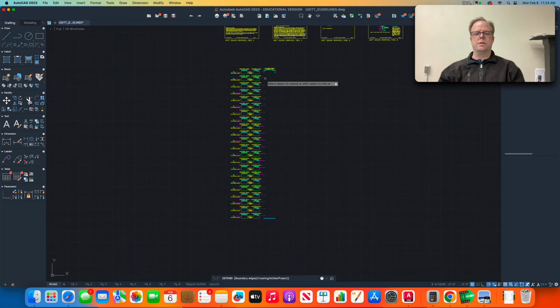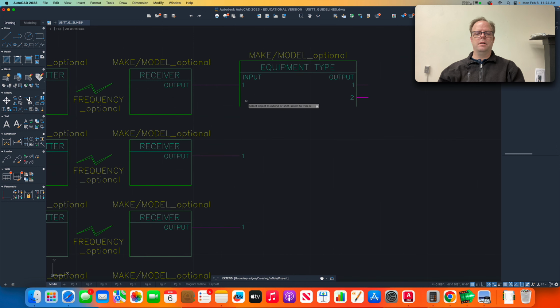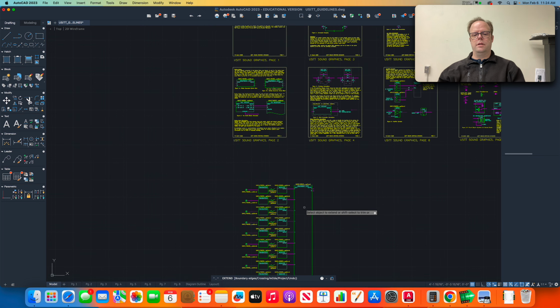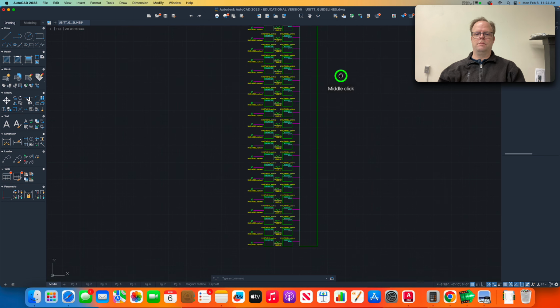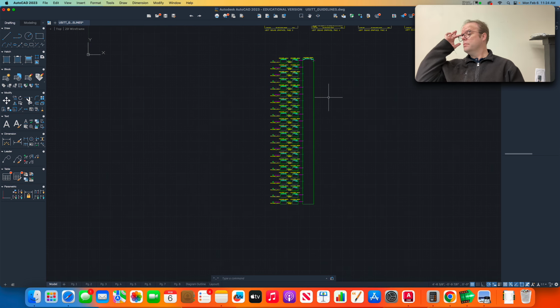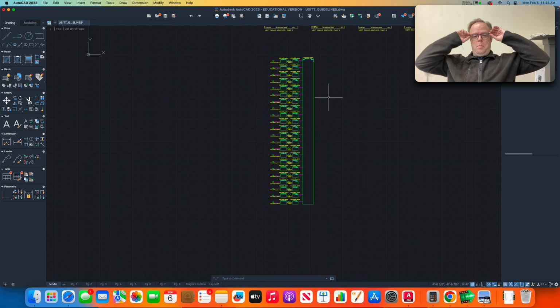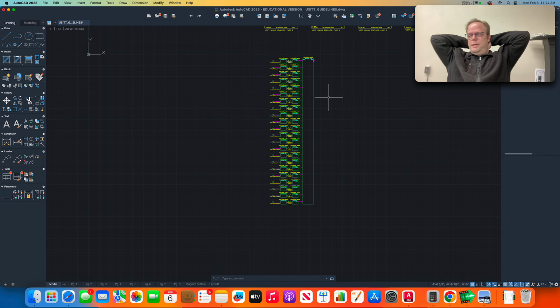Select the objects to extend. So I go back to the top here, and I click on the left side one, and I click on the right side one, and then hit enter to get out of the command, and now it is extended. And I've effectively grown that whole thing. Yeah? That make sense?